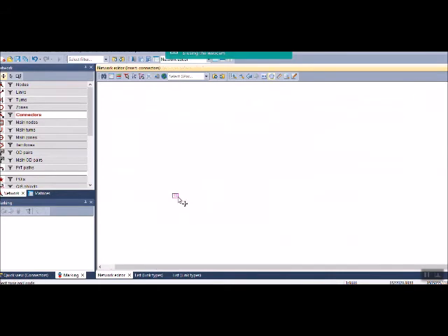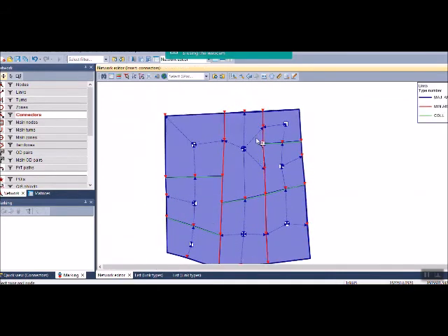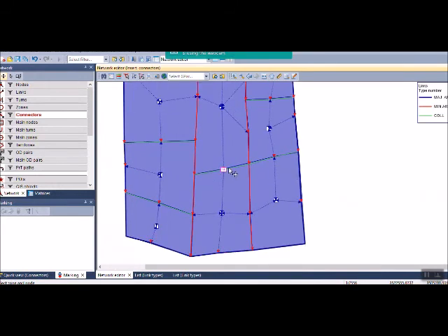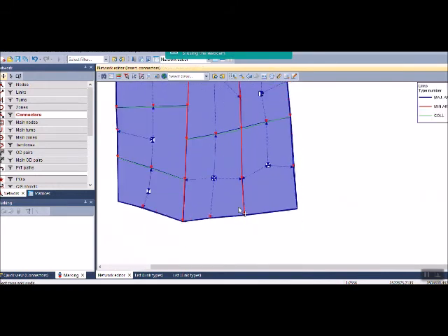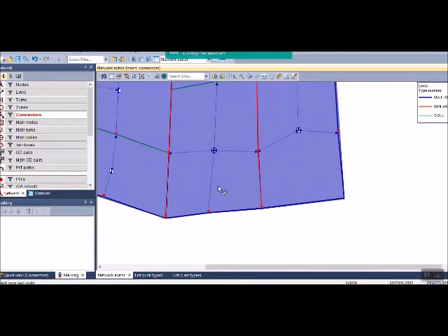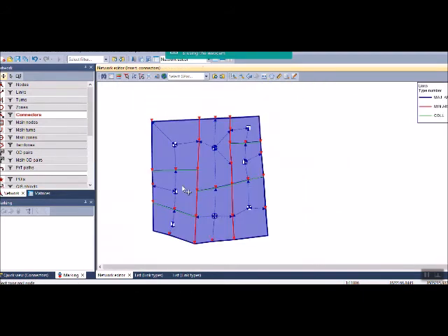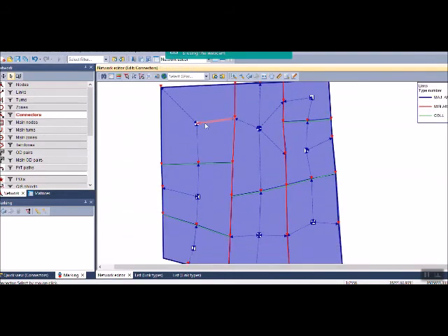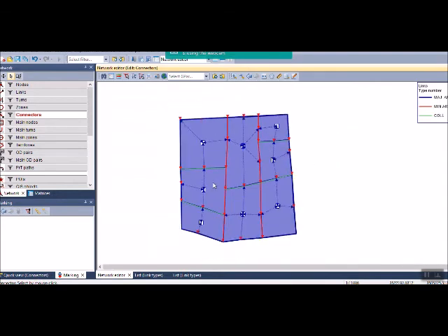But in this example, I don't know exactly where the local roads are intersecting the main network, so I assumed some points on the roads which are acting as an intersection between the main road and the local road. These connectors are not going to be analyzed, but are just connectors to move the vehicles from the centroid of each zone to the network which we have built earlier.